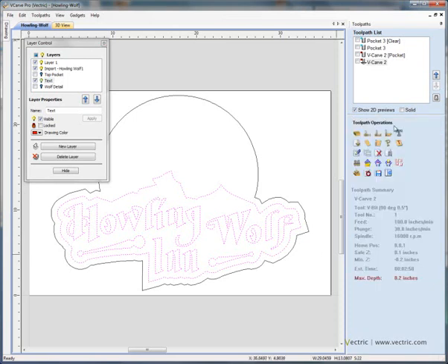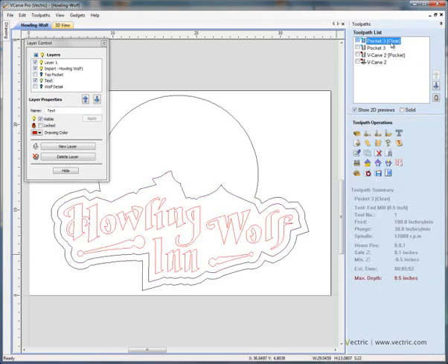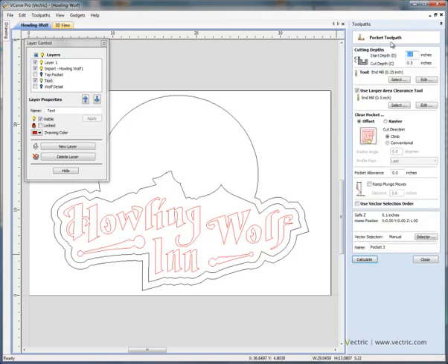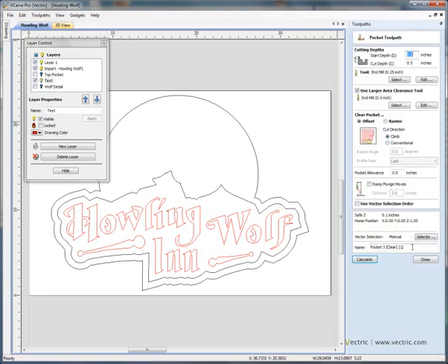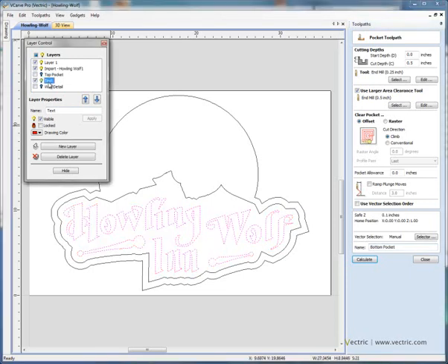So we go back to the toolpath operations. Now we've already done this, a pocketing operation using a 1/2 inch end mill and a 1/4, and I'm going to use the same toolpath setup for this bottom area. So if we select this toolpath and we say copy, okay, so now we've got a toolpath here that's a duplicate. Let's double click and let's call this bottom pocket region.